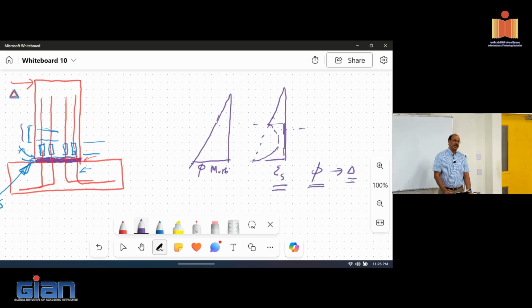In other words, your strain has to increase. That means this area of strain will continue to increase compared to a cast in place. The more restriction you put in, the more localized strain you'll see, and you're more likely to cause early failure because you're straining that location more and more. So anytime you see a large crack, it's a concern because you're concentrating strains.